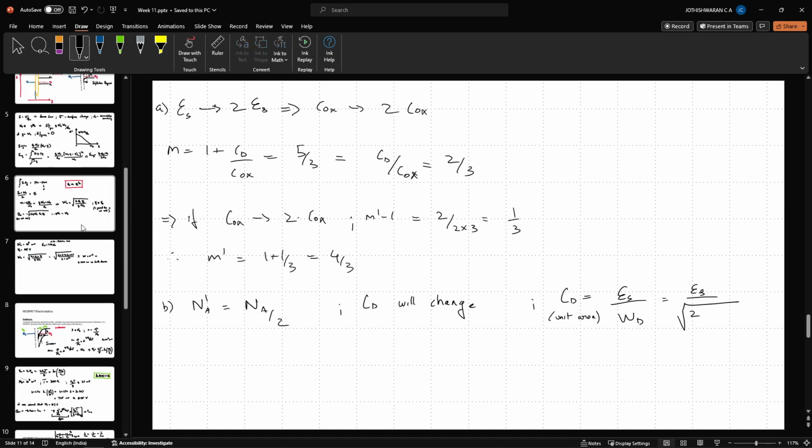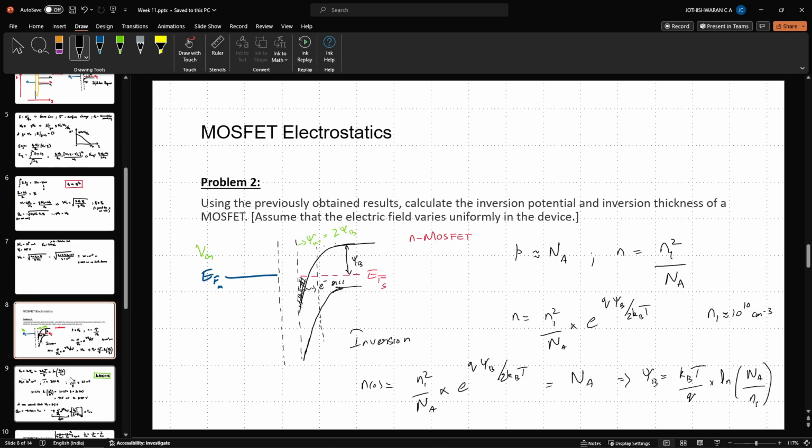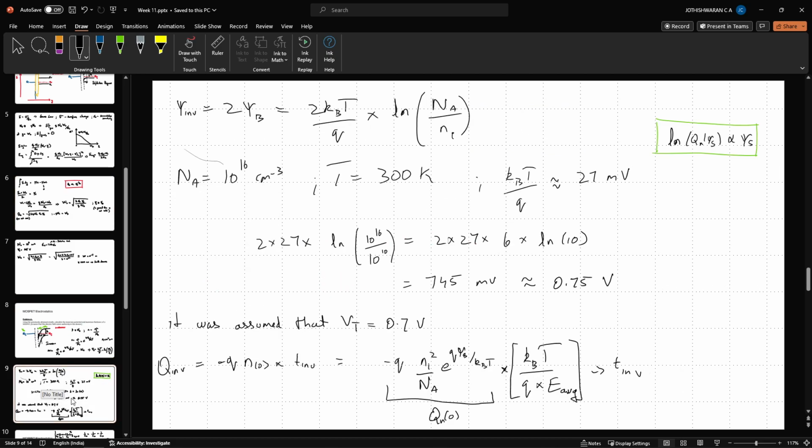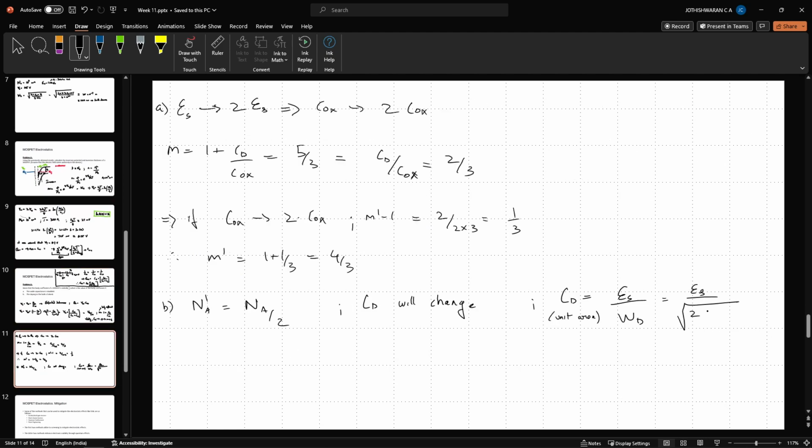Let me just go back to be doubly sure. Yes, WD is the square root of 2 epsilon s psi s divided by q times Na.